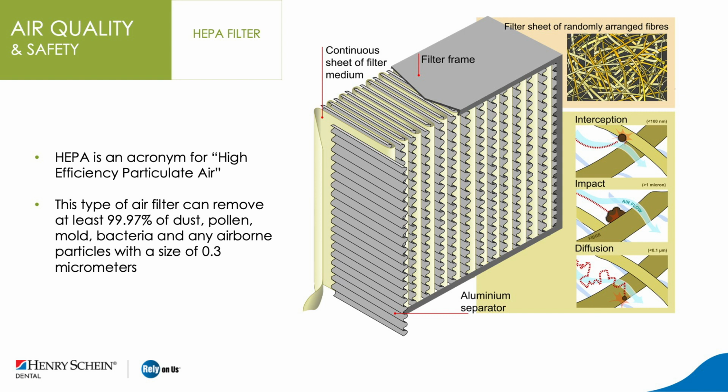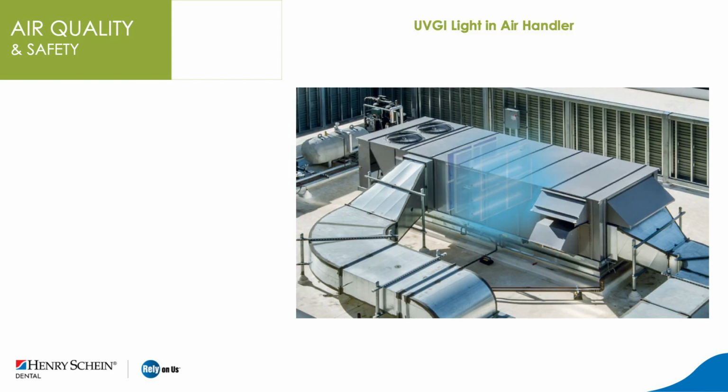In other words, we've got a heating and air conditioning zone for the clinical zone, one for the public zone, and one for the private or staff zone. And this way, you don't have a war of the thermostats. If you have the team working in the clinical zone and they want it cooler, they can turn the air conditioner down, and the people in the public zone won't be cold, and the people in the staff zone won't be cold.